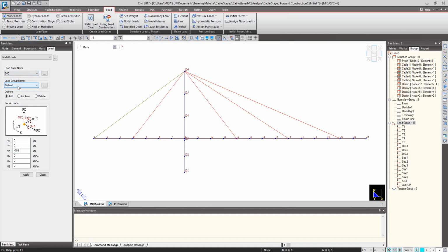And that's quite important and also useful, because you can set up a load case with many loads, but then if to the specific load you assign a different load group, then in the construction stage analysis, they will be treated separately. The way of thinking about this is that the load groups for the construction stage analysis are like load cases.